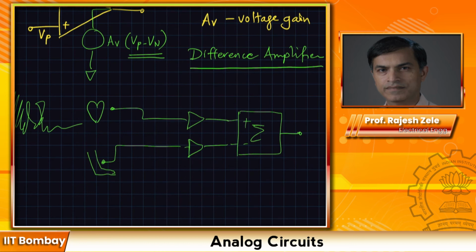The kind of signals we are trying to detect, for example between the heart and your leg to do an ECG, are really small, less than a millivolt. Here there is something like 50 to 100 millivolts of 50 hertz hum riding on each side. So there is a 50 hertz tone here and a 50 hertz tone over here.